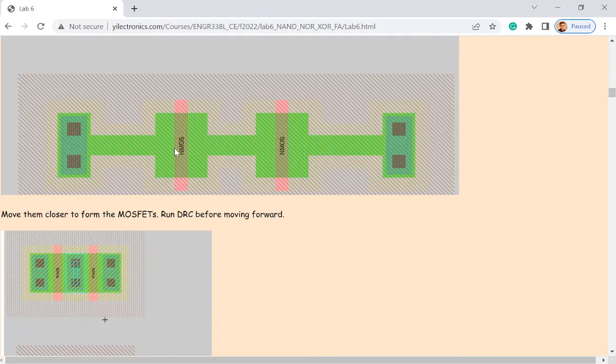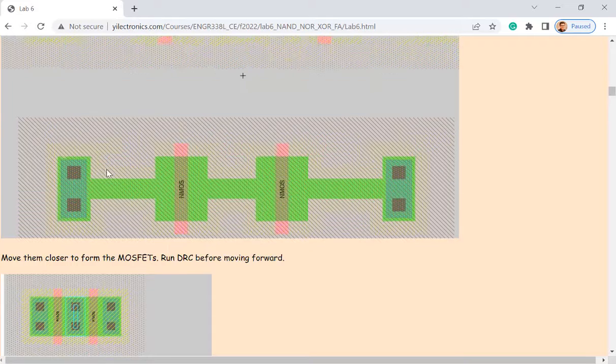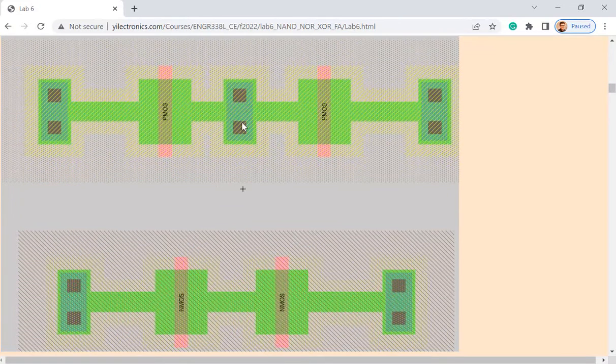Yeah, we have to. So you grab the NMOS, you grab a via and resize it, and then connect them using the green wire, which is diffusion, and then you move them together to make an NMOS, right, on both sides. But when you are making 2 NMOS in series, you don't add a via, via diffusion to metal 1 via in the middle, but you directly connect them using the green wire. Now it makes sense why you do that, right? They are the same node. Why bother adding another via? Just short them together. So the question is, why we need that thing here for the PMOS?